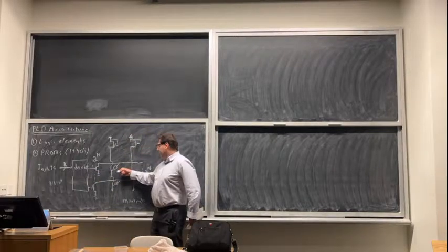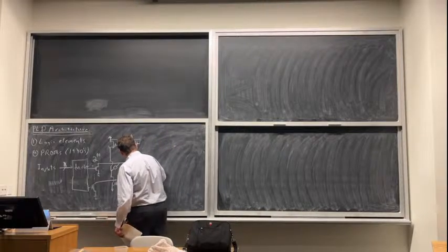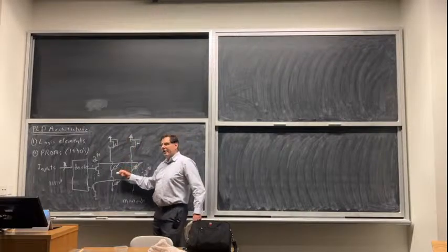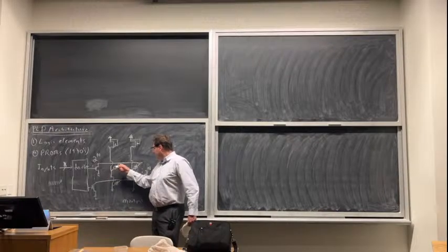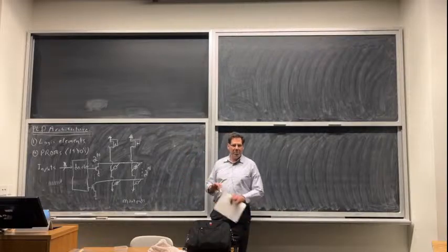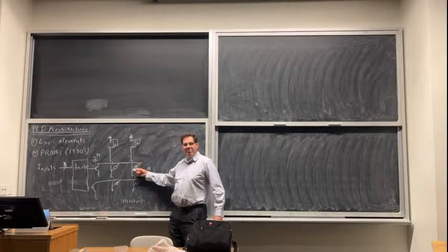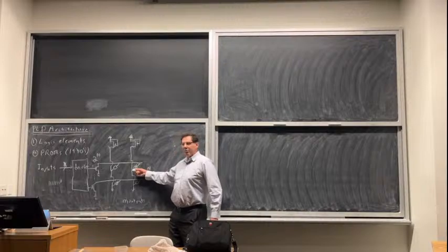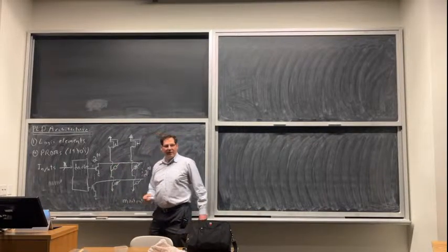And the way this makes programmable logic is we have fuses. The programming technology in these were fuses. A fuse means it's initially connected, so this wire is connected to this wire. But I can destroy the fuse. I can blow it using some technique. Often it could be a higher current, could be something else. But I have some mechanism to program this device after fabrication by blowing the fuse. So this fuse has been blown, so this wire and this wire aren't connected. This wire and this wire still are connected.